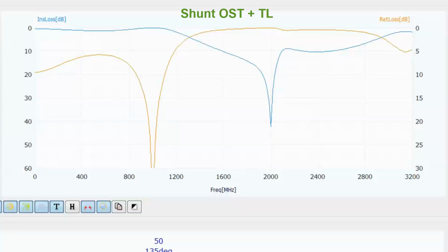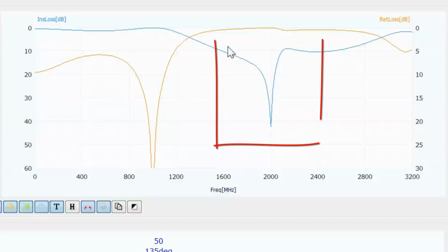Of course, the return loss, the S11, will be minimum at the frequency that you aimed for at 1 GHz. And that is because obviously you designed to have a very low reflection coefficient at the frequency of interest so as to have maximum power transfer to the load. However, on the insertion loss, you can see that although at 1 GHz your insertion loss is very low, and this is what you want, when you go up to twice your frequency, all of a sudden the insertion loss drops dramatically. This means that basically you're getting effectively no power transferred to the load at all.